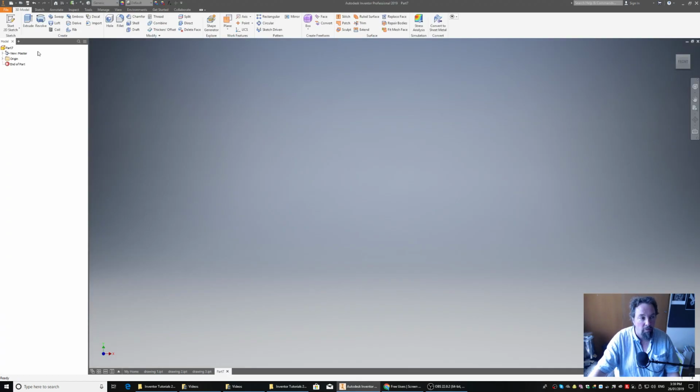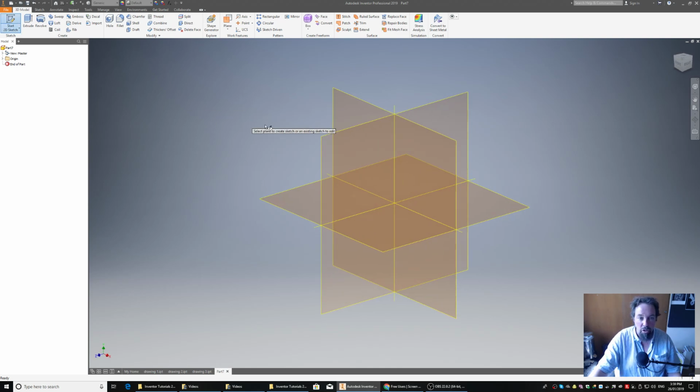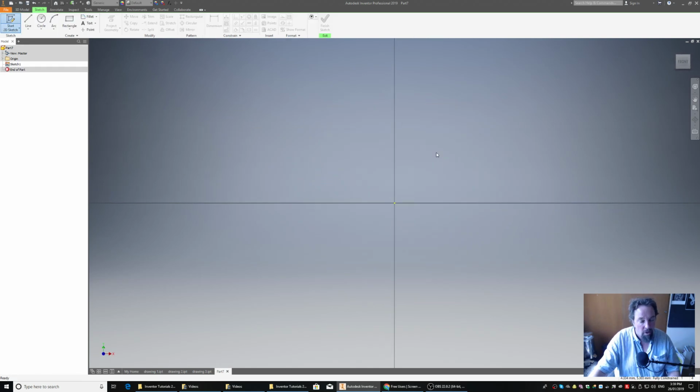Again, go back to the top left hand corner, Sketch, choosing the XY plane, still nothing's changed. And this is the first time we're going to do something a little bit differently. In this case, we're going to draw a profile and then use dimensions to set the sizes for my drawing. So instead of using a rectangle, I'm going to choose the line tool. Now with this technique, it doesn't matter what length your lines are, it's just that you get the shape basically right. So here we go.